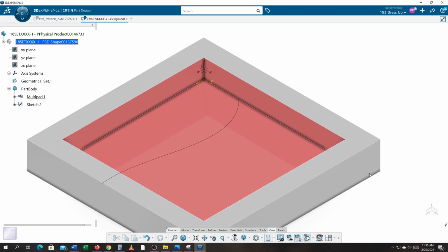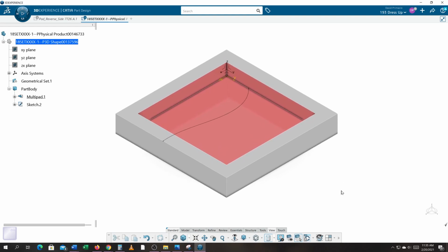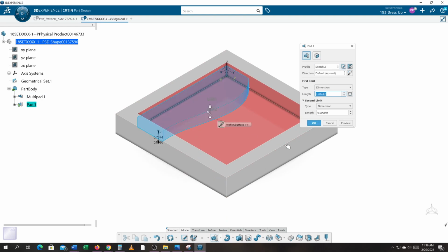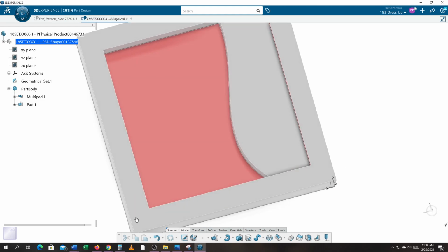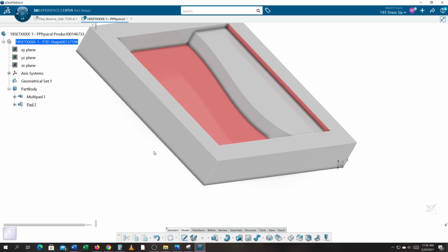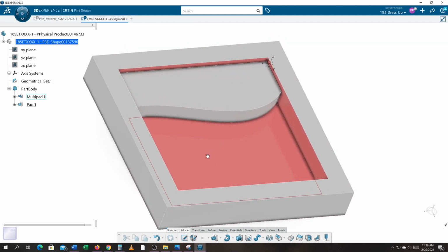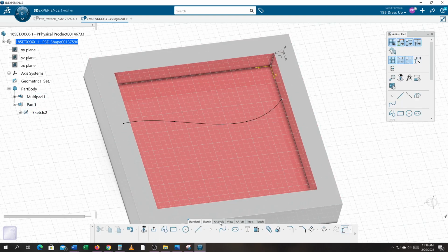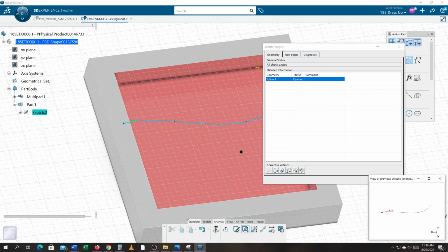I'm going to try and make a pad using this sketch. I'll select OK. No problem. Got my pad in there. And what's really cool and different about this, one of the questions is, what's different about this pad? Did you notice I didn't have to make a closed profile when I was in this sketch? I knew I didn't have a closed profile. I didn't analyze it. It's going to tell me it's open. And yet I was able to make a solid with an open profile.